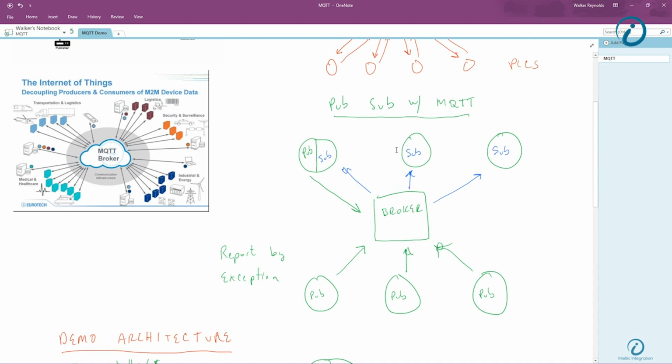So up here I have a device that's just a subscriber. Let's think that this is a web application connected to the broker, and it has told the broker, I'm subscribing to 3 tags: temperature, humidity, and sunlight. The broker just keeps track of those 3 topics. Maybe they come from instruments out here, and when they change, they get pushed from the instrument to the broker, and the broker pushes up to the subscriber. Only the values that changed.